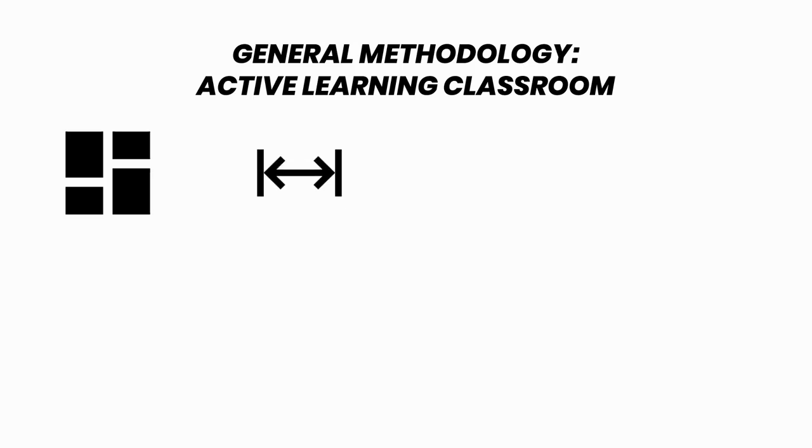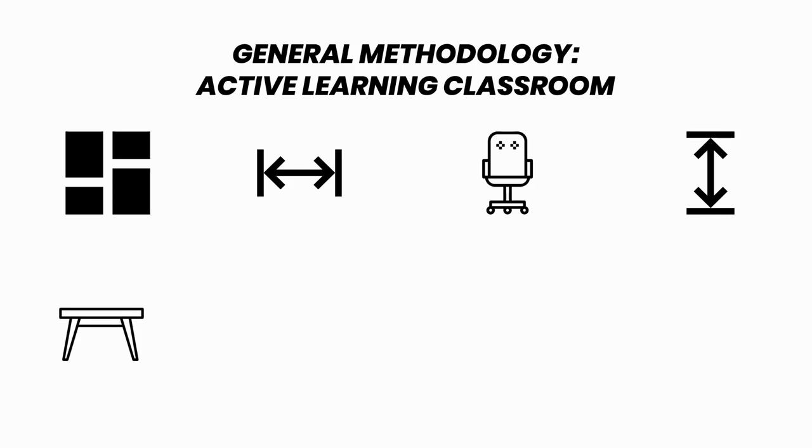We will now be discussing our general methodology in designing an ideal facilities planning classroom. First, the shape of the classroom will follow a rectangular form to maximize space utilization. Standards will be followed for the allowance of 50% of the occupied space and a chair area of 0.42 meters by 0.4 meters. The first row of seats should ideally be a minimum of 9 feet from the front of the room. An 8-seater desk to accommodate the active learning principle will measure 1.8 meters by 1.2 meters.